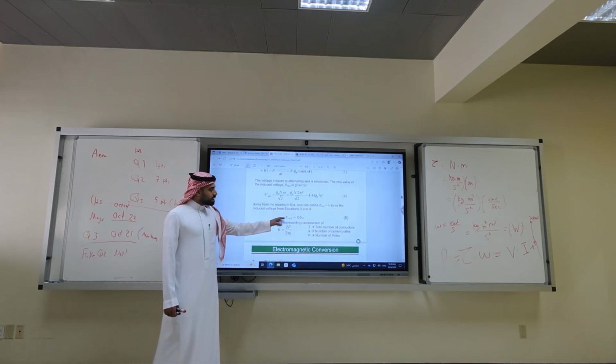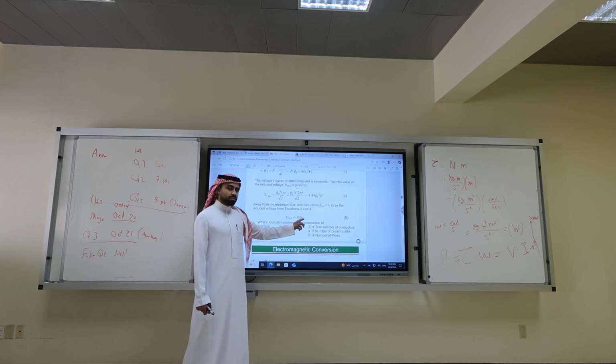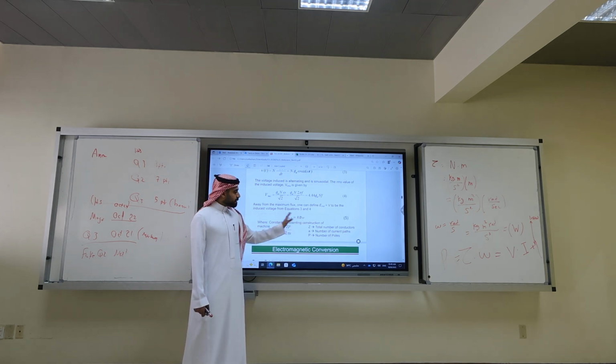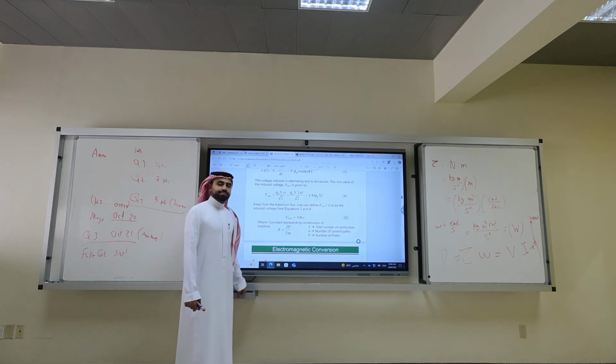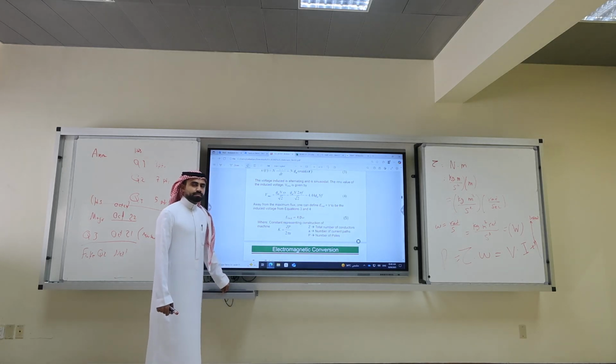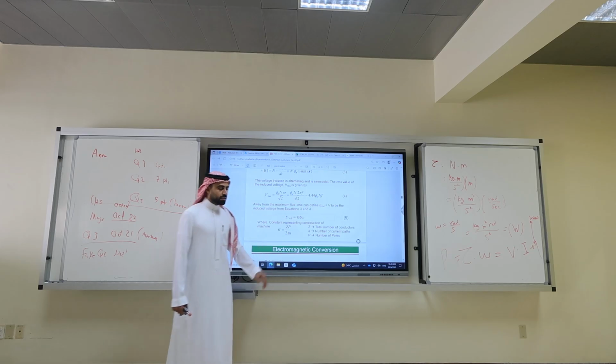But that's the thing I'm telling you about this equation. Induced voltage is K times flux times omega. If you put RMS, this has to be RMS. With speed, this is speed. If you put a function of time, this is a function of time. Don't say K is this number. No, K is this number.